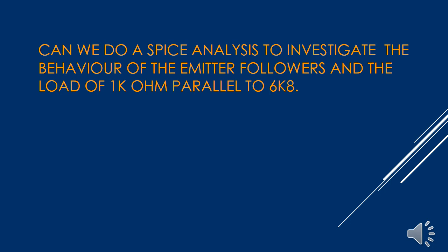Can we do a SPICE analysis to investigate the behavior of the emitter followers and the load of 1K and 6K8 in parallel, which was the case? Therefore, if we do a SPICE analysis, we don't need the input FET, so it's gone. And then we have this schematic, and we should put that in a SPICE analysis schematic, and then it looks like this.